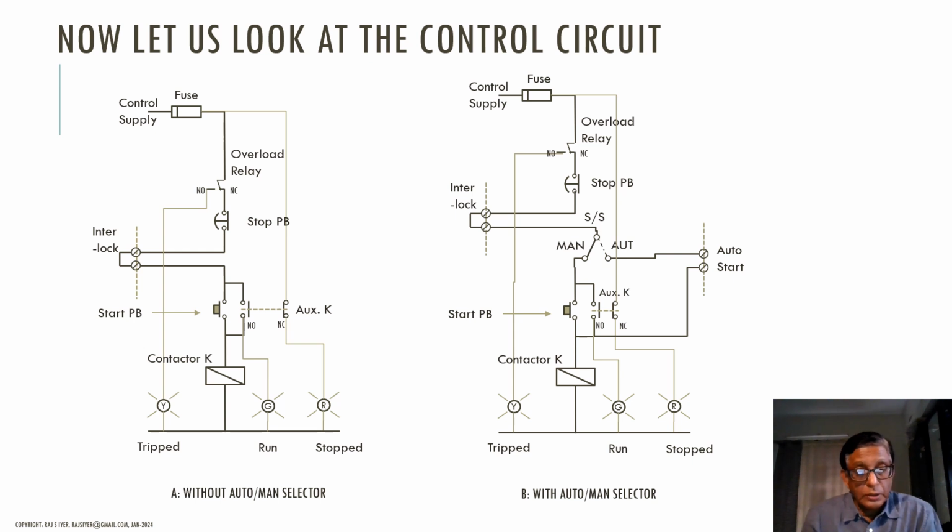Now to stop the motor, of course, we de-energize the contactor by using the stop push button, which disconnects the control supply to the contactor, and the contactor opens, the contacts open, and the motor stops.